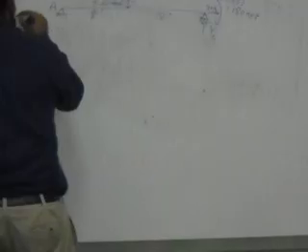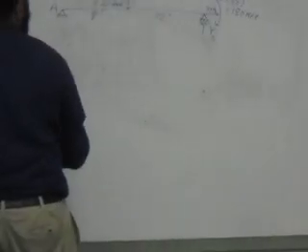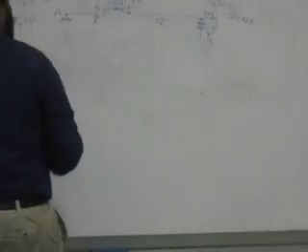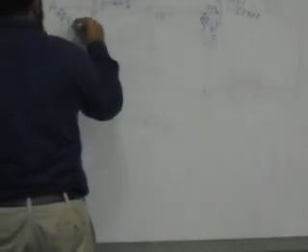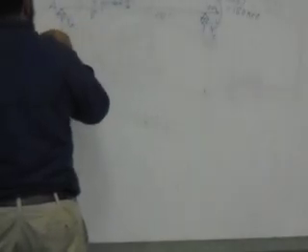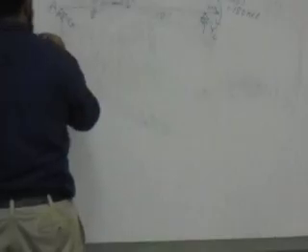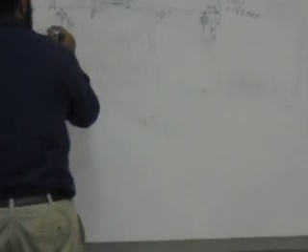Sigma Fy equals 0 equals: I'll have the 8 that I just calculated plus YA minus 5. Note that the moments will not affect the sigma Fy at all.